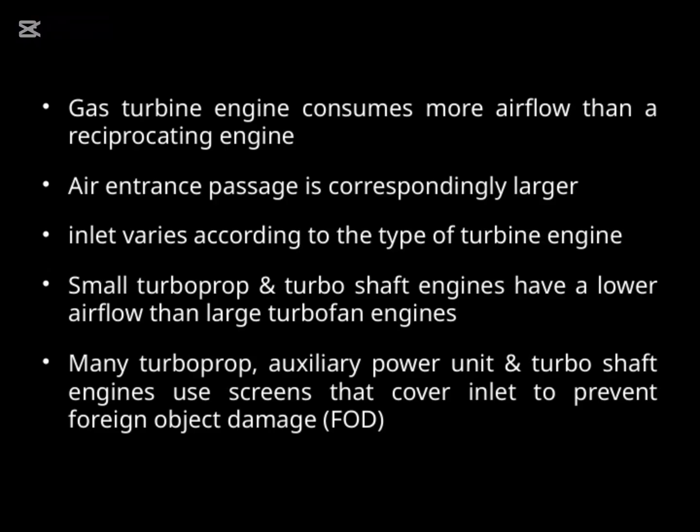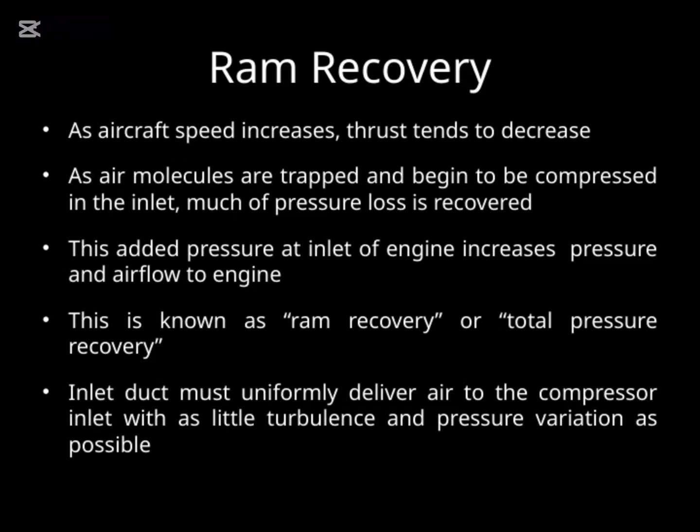You'll also notice that many turboprop, auxiliary power units, and turboshaft engines use screens over the inlet. These screens serve an important purpose. They help prevent foreign object damage, or FOD, which can be a serious risk to engine components. So, in essence, the design considerations around airflow and inlet size are crucial for engine performance, safety, and longevity, especially given the different sizes and applications of these turbine engines across various aircraft.